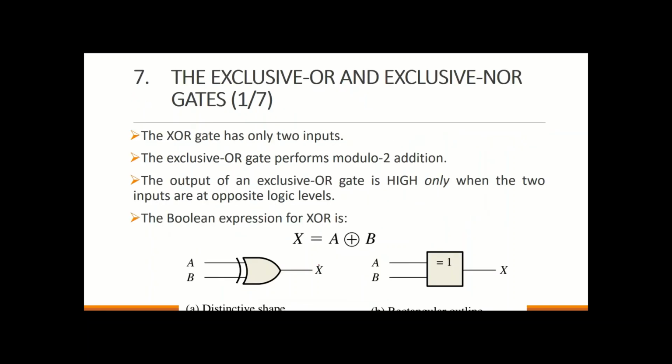We have the exclusive OR. The exclusive OR is exactly applying the addition of modulo 2. The modulo 2, you guys are familiar with it. It's the remainder of the division by 2, and that's the exclusive OR. It's an OR gate exactly, but with just one curve covering the inputs, and that's the exclusive sign. It's referred to by a plus with a circle telling that it's an exclusive OR, XOR process. Okay, in the rectangular outline, it's not greater than or equal, it's directly equal to 1.